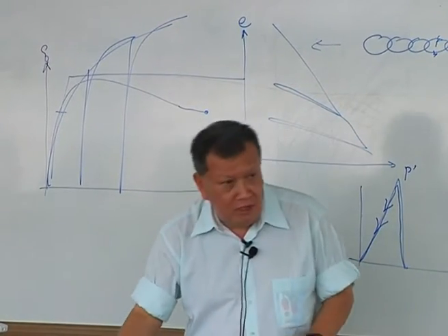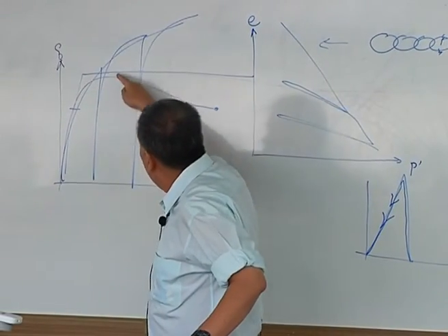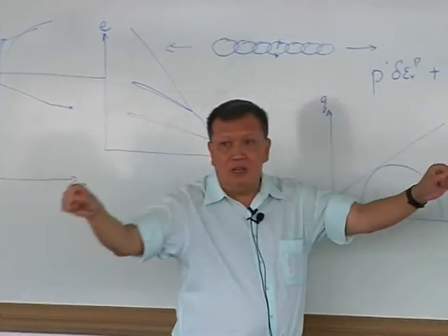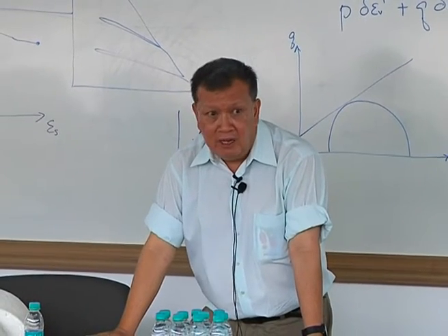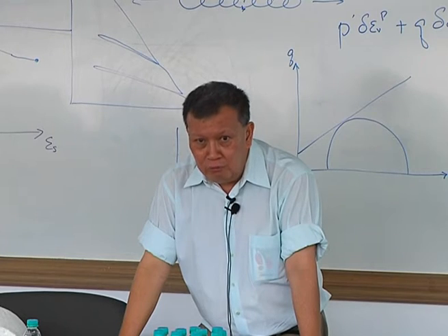Now, for mild steel, it's the same thing. The mild steel stress strain curve is very complicated. It comes up, down, and then goes up this way, and then slowly goes up there. But people will just use an elastic, perfectly plastic model. They're quite happy to do that. So it is not as if the soil people are the first ones to do this kind of thing.